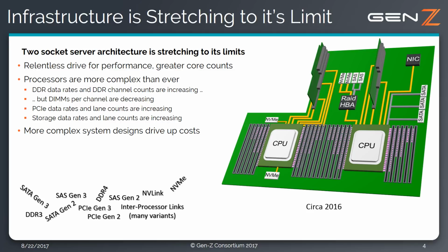Another technology that emerged in this time frame was NVMe, which allows solid-state disks, or SSDs, to be accessed directly over PCI without conversion to SAS or SATA protocols. The number of CPU cores was increasing at an ever faster rate than the memory and the I/O bandwidth of these devices. Again, the CPUs had significant growth in size, pin counts, complexity, and cost. This also increased the complexity and cost of the motherboards for these servers.